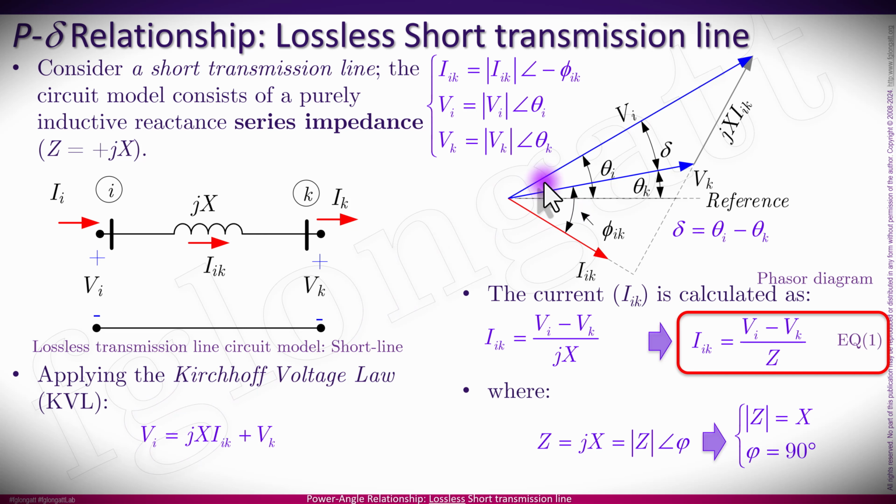Then we can use in this phasor diagram the voltage drop through the series reactance, and adding the phasors, you can use just basic trigonometric principles. You can obtain that this phasor that is in blue color, the larger one, is basically representing the sending voltage.